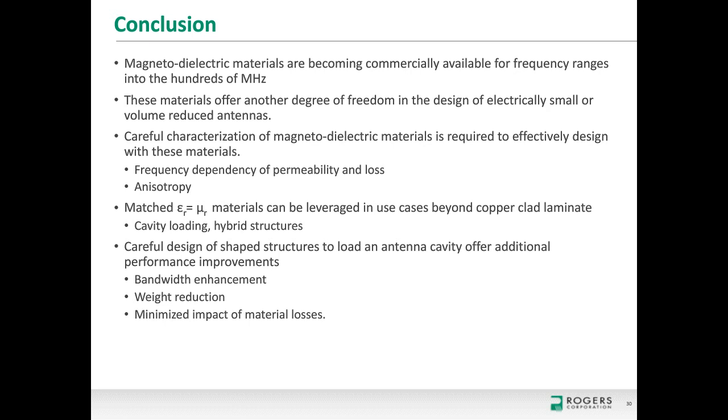You want to operate at a cutoff frequency. You want your material for low loss to be something like 1/5 of the cutoff frequency of the material. So from a 500 megahertz low loss frequency, my cutoff frequency needs to be at about 2.5 gigahertz. Different families of materials will have a different intrinsic product, but generally you're looking at an intrinsic product that's in the tens of gigahertz.